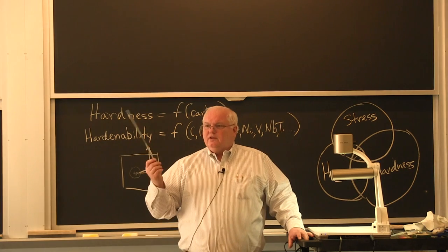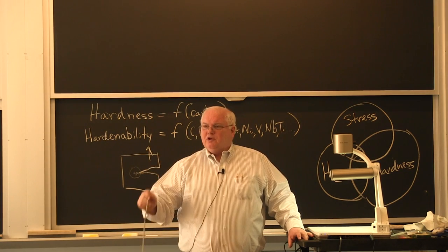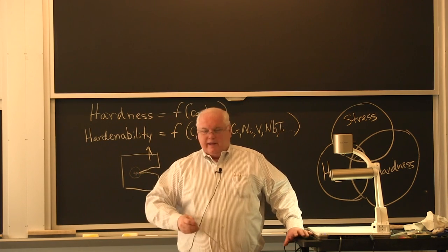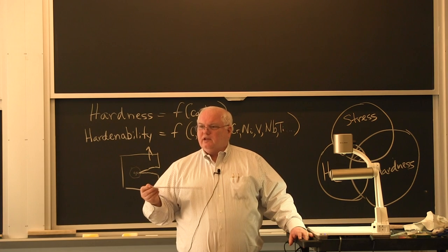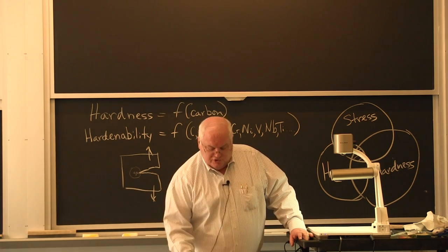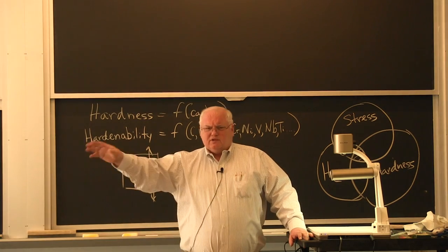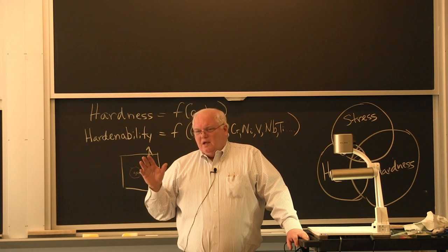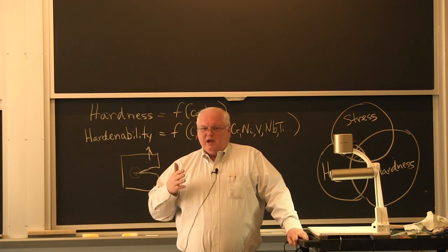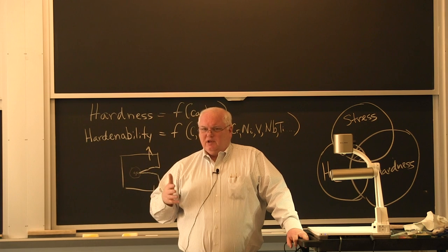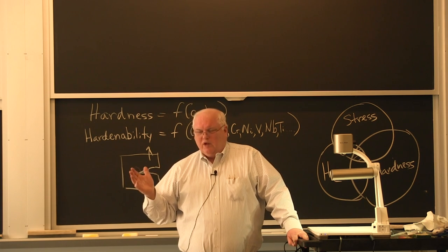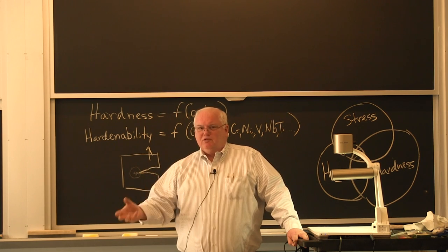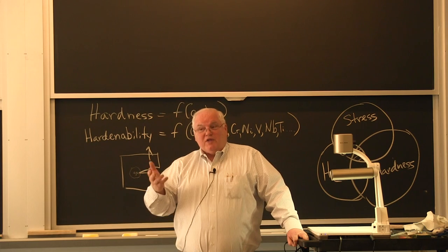A guy in Göteborg, Sweden, found that sticking his bare electrode in the mud at about 1910 and welding with a muddy electrode excluded all the porosity that came from welding in the air, in terms of the nitrogen in the air causing porosity. I go through this in my fusion welding class, okay, in a little more detail. But anyway, that in Göteborg, Sweden, became the beginning of what's now known as the ESAB company, which is one of the world's largest welding companies. But they learned to use muddy electrodes. They were basically using minerals from the mud, okay? But they had a lot of moisture.